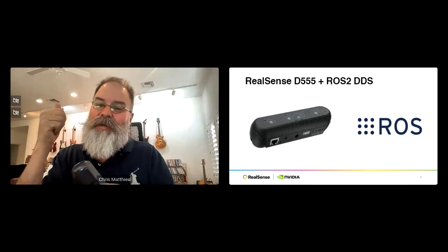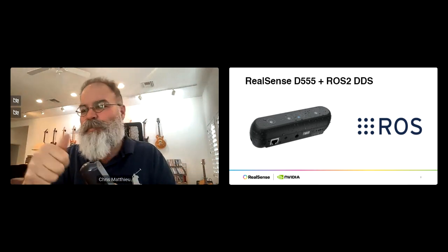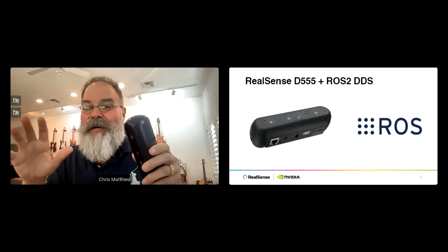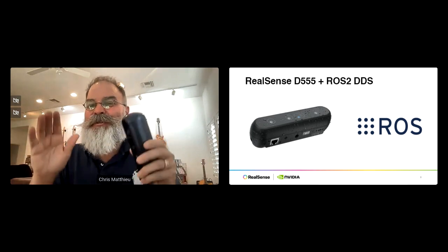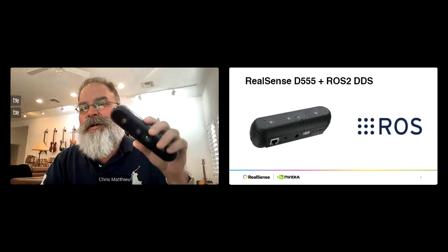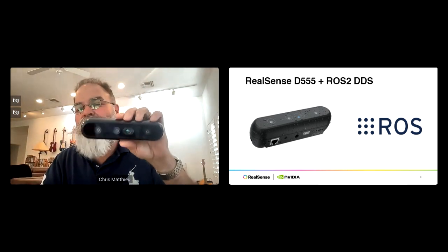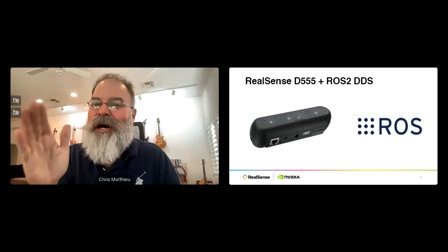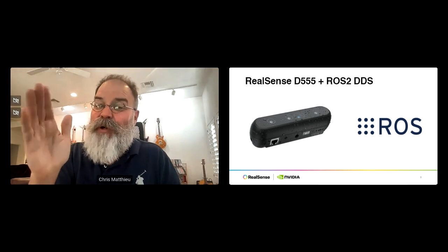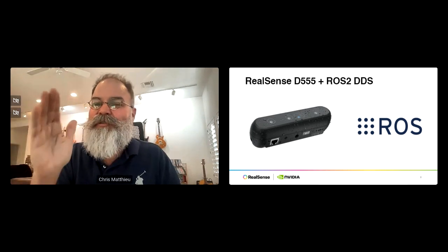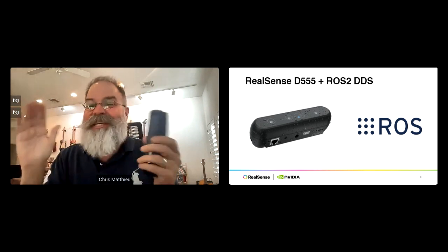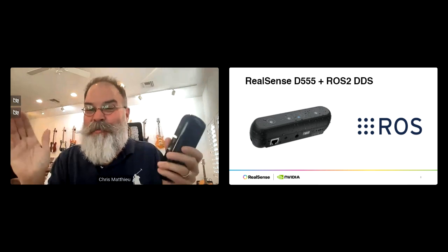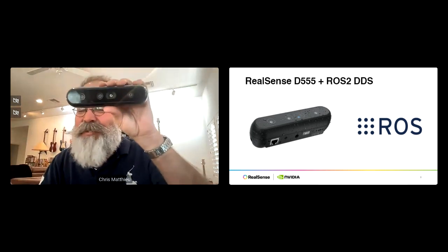The RealSense SDK is open source, PyRealSense 2, all of this stuff. I just said, hey, Cursor, can you use the image raw stream that's coming in on ROS of the 555, and can you just tell me, is there a person or not in the frame? And then if there's a person, I said, follow the person using ROS 2 twist commands. So I kid you not, in 10 minutes, I had my follow me robot working, following me around on stage, because I didn't have to do any configuration.